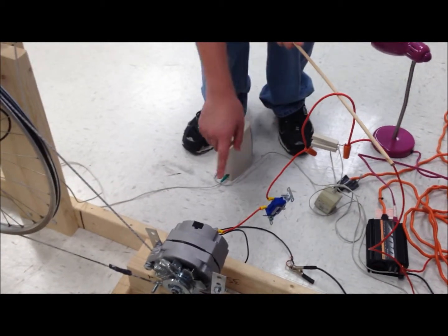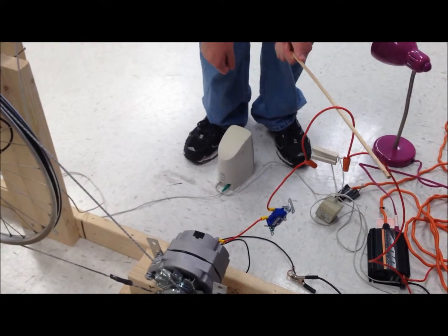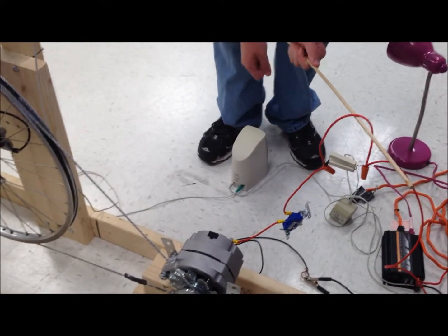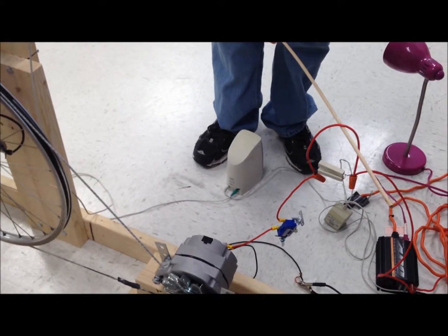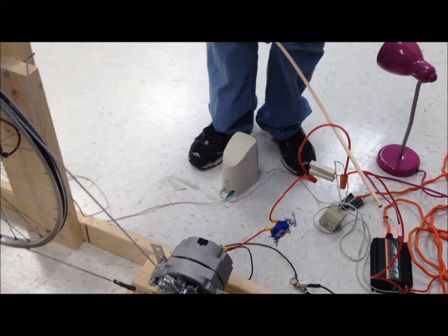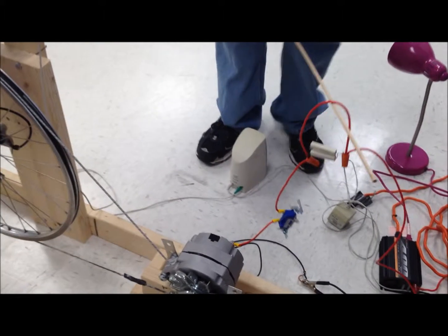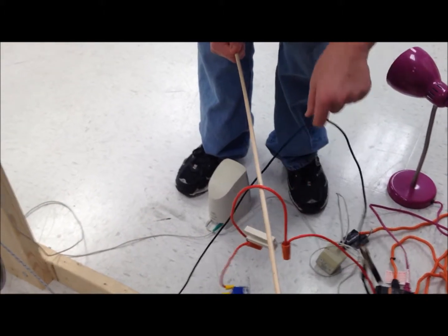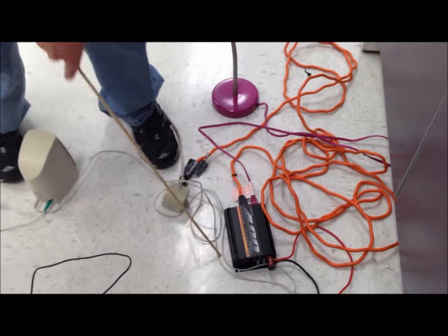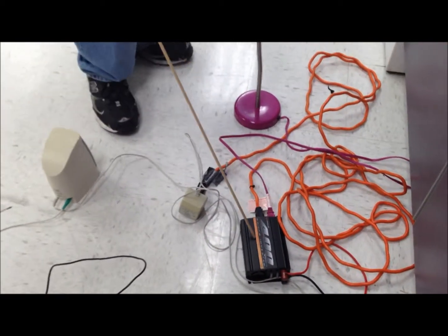The resistors were wired in parallel because we researched the proper amount of resistance for this project and found the number 0.47 ohms. By linking the resistors in parallel, the resistance now equaled 0.5 ohms. Although there is a slight difference, it is not large enough to affect our generator. Both the positive red wire and the negative black wire are connected to an inverter that converts direct current to alternating current. The alternating current can now power any common appliance.